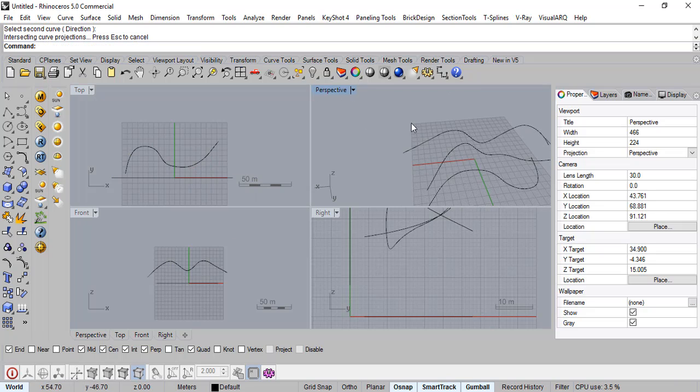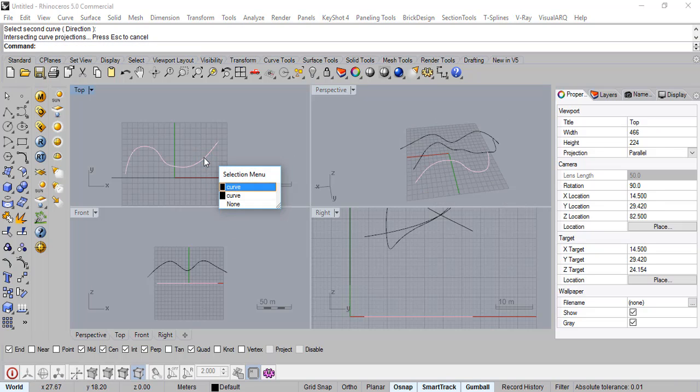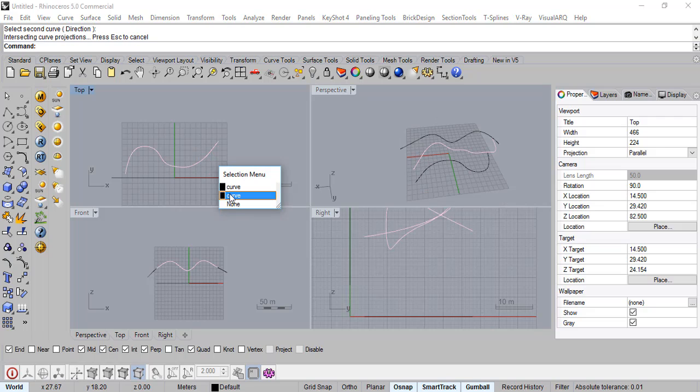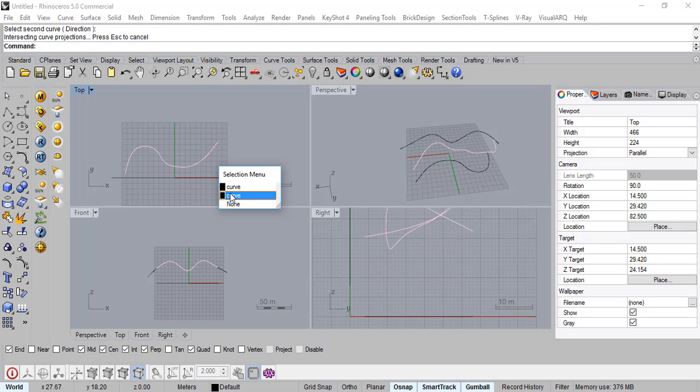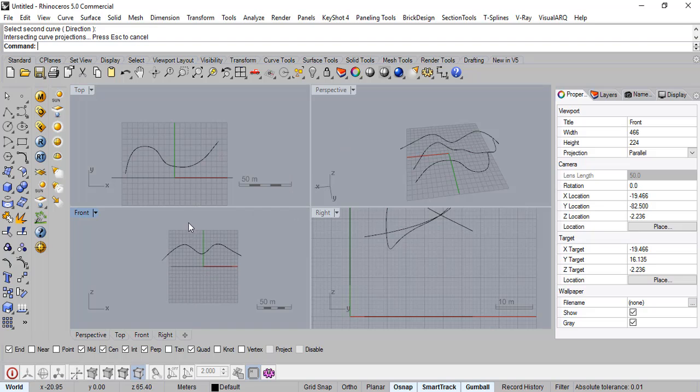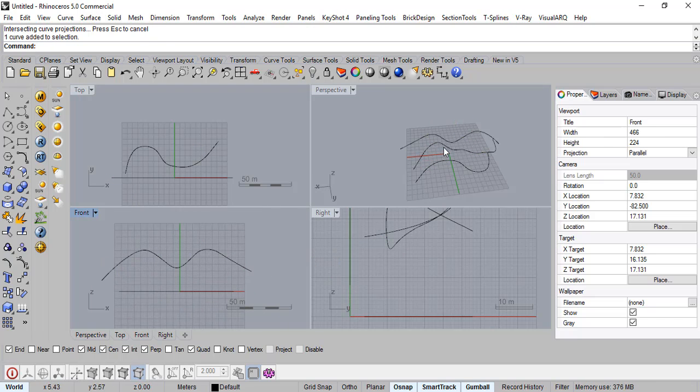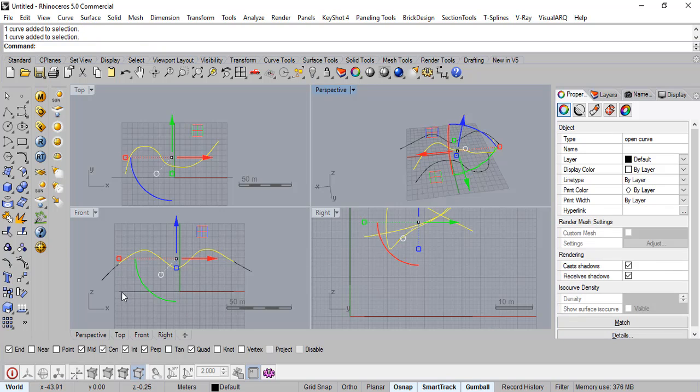If you look very carefully, if I click on this, there are two curves. See in the perspective view, this was our original one on the ground, this is the new one. So it has trimmed away that part automatically. Are you getting this? You might want a shape like this, but you won't get it; it gets trimmed away. It aligns it with the first object.